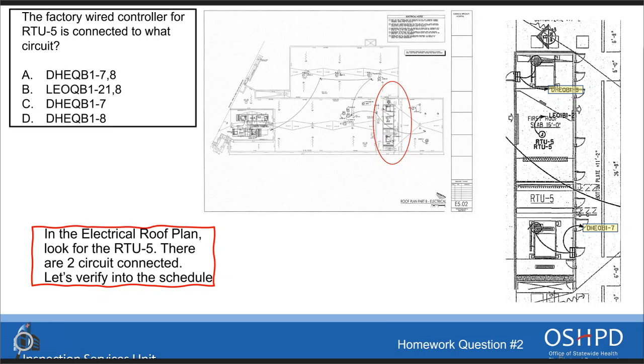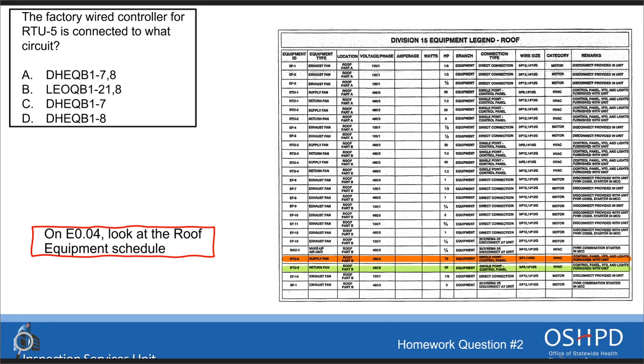If we back up one slide, Caesar, the way I interpreted it is that there's two controllers. The reason I came to that understanding is because of the mechanical equipment schedule, which indicated in the remark on the left, it's control panel, VFD, furnished with unit. So you're right, it doesn't necessarily say how they're circuited, it says it's furnished with the unit.